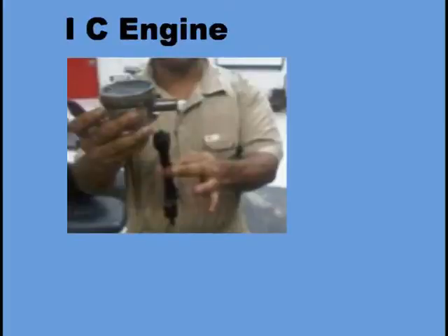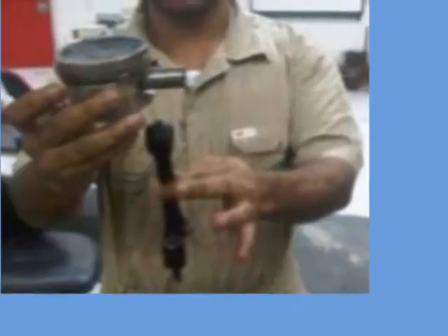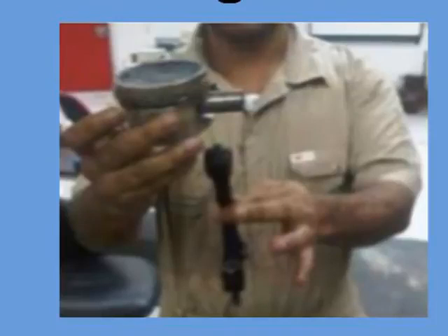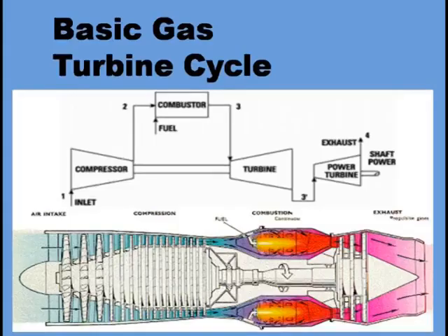Another view is also shown of how the connecting rod is connected with the piston. One pin is visible, known as the gudgeon pin. One end of the connecting rod is connected with the piston with the help of this gudgeon pin; it is known as the smaller end. The other end is the bigger end, which is connected with the crankshaft. So, the reciprocating motion of the piston, with the help of the connecting rod, transmits power to the crankshaft, and the crankshaft rotates.